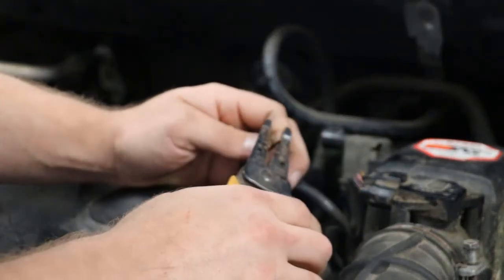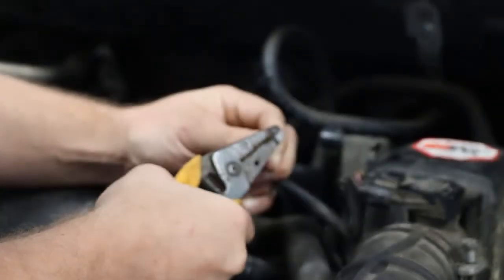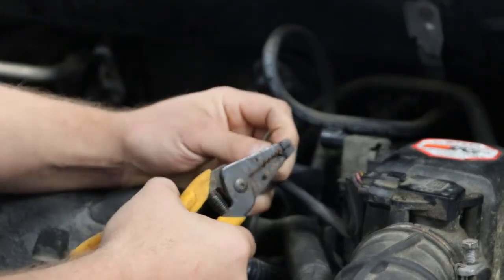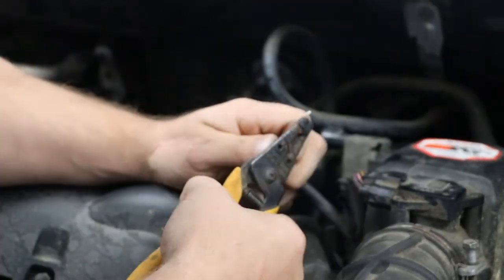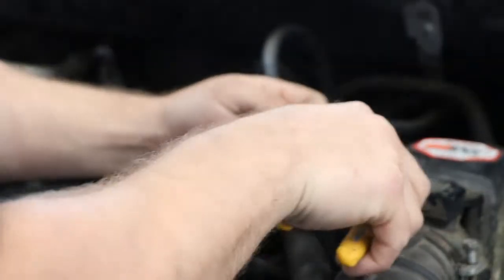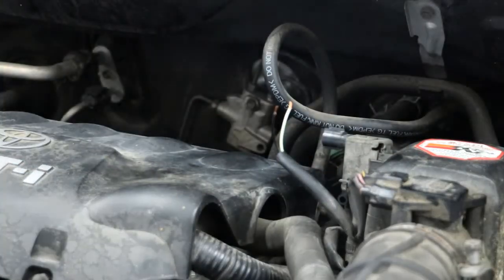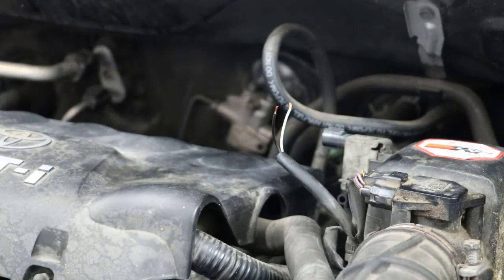So I have a really small wire cutters here, and I'm going to just run it around and go ahead and strip that off. And I have one more here. I'm going to try to make sure it's even. Hold the wire firm, strip this off. Awesome. So now we have two ready-to-go wires here. I'm going to go ahead and cut small pieces of the shrink wrap that I'm going to pre-place on there before I add my new wires.